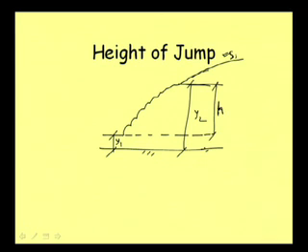Now whether we will consider the height of jump as from here to that point, it is not. So we should be able to identify where the jump is actually ending, and that particular level we need to know. That observation is very critical, because finding where the hydraulic jump ends is really difficult, because some waves will be there. So we need to take care in observing the height of jump. Okay, and then we will be discussing another point.